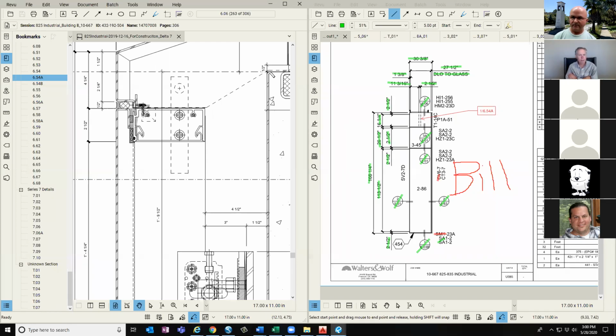No, I mean, on this detail right here, you can get rid of that gasket, get rid of that filler, and take that angle and make it field use. Make everybody's life easy, because they have to take that angle off just to put the membrane in. You can't put the membrane in the way it's shown, so there's a big problem. And we've also heard from the PM that the angle should be on, just don't cock it, let the field pull it off. That way it's there and the holes are lined up.